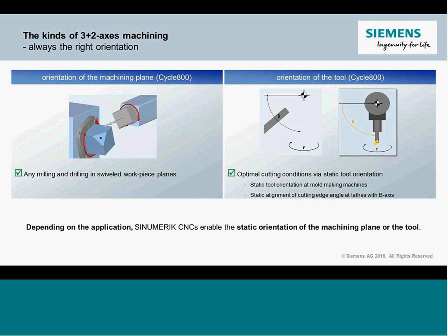What's happening with the beta and the gamma fields, right? That's really doing that orientation of tool option. I want to create a plane and then have my Z orientation be perpendicular to the plane, and then the tool automatically aligned to that plane. I'm going to use the orientation of the machine, and that's what we call our swivel cycle.